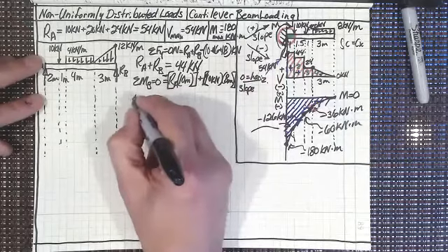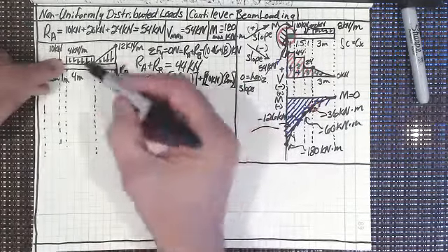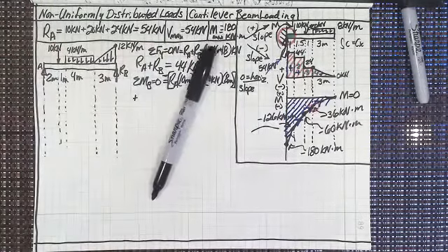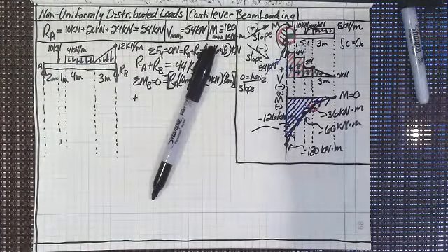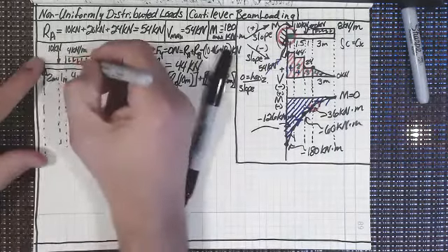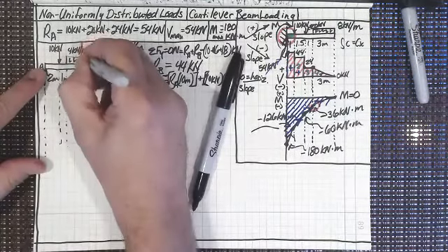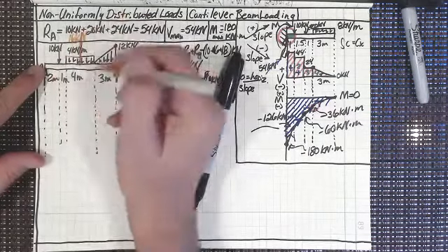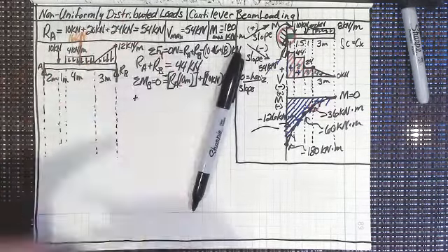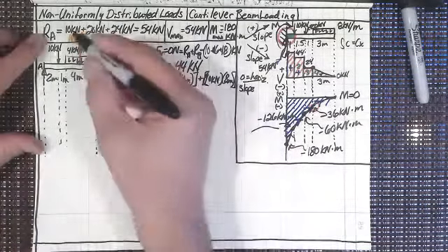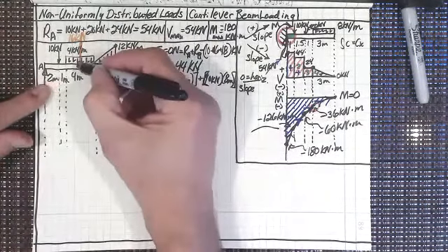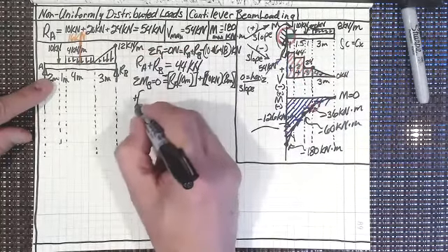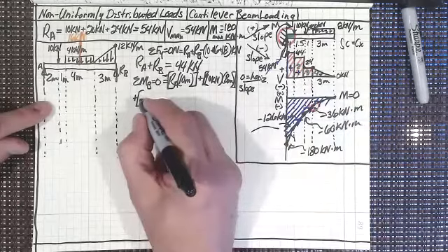I'm going to extend it over here, plus, now what do we do with this 16 kilonewtons? It's right at the centroid, right? So it's right in the center there is where we're going to put the 16 kilonewtons. Right in the center, right in the centroid. And so 16 kilonewtons, and then how far am I going? 3 plus 2, or 5.